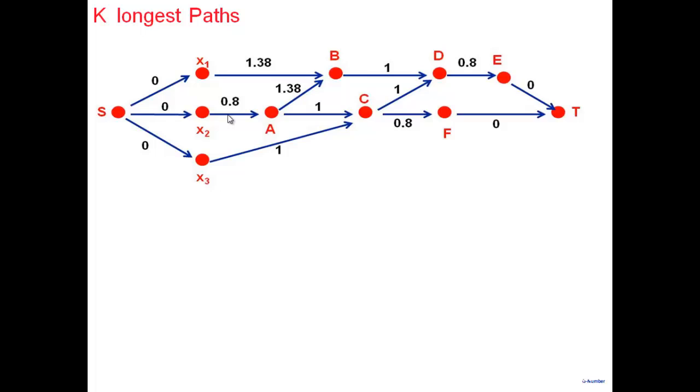So what we are doing is top-down design, right? You start from the top, the specs, and gradually you do RTL and the gate level. So I've come to the gate level. But remember, I have a lot of choices to make at this stage, because if I'm not meeting timing constraints, I may have to decide, well, one adder is not enough, or I use a ripple carry adder. Ripple carry adder is not good enough. Look ahead carry adder. I may have to take a decision.